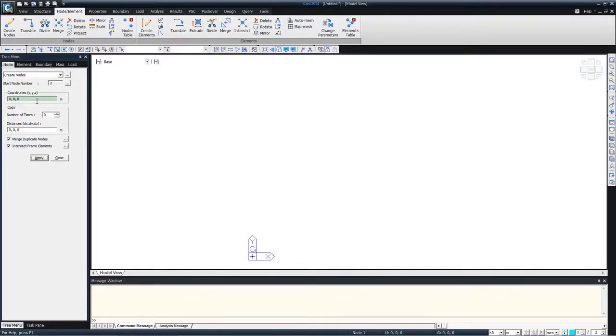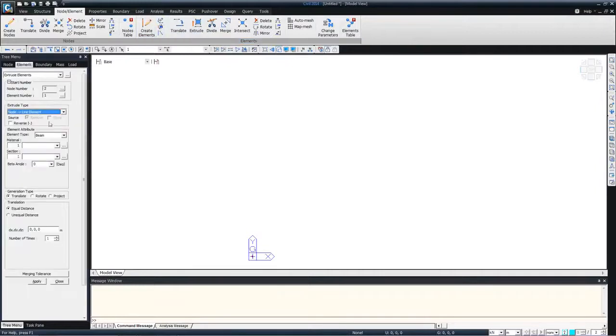So what I will do is create a transverse line, which will represent the reference line for the skew. I'll use this node, select it. The selection tools are similar to AutoCAD. So selecting this and extrude, just enter how many divisions I want on that line. Say in the Y direction, 4 at 3 meters, for example. Apply.